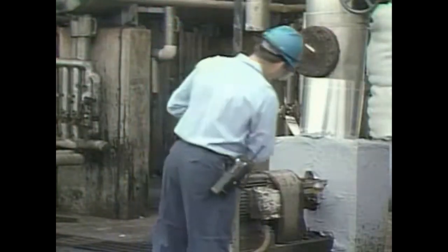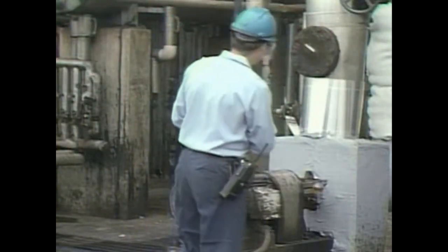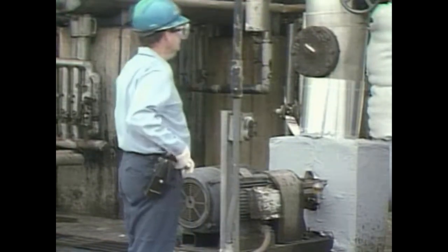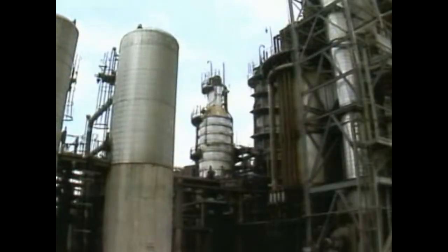After the equipment in a distillation system has been readied for operation, the startup of the system can begin. To demonstrate typical cold startup procedures, we'll use a vacuum distillation system that separates a non-combustible binary feed mixture. Now, if a combustible mixture were being distilled, a precautionary step called purging would have to be performed before allowing the feed mixture to enter the column.